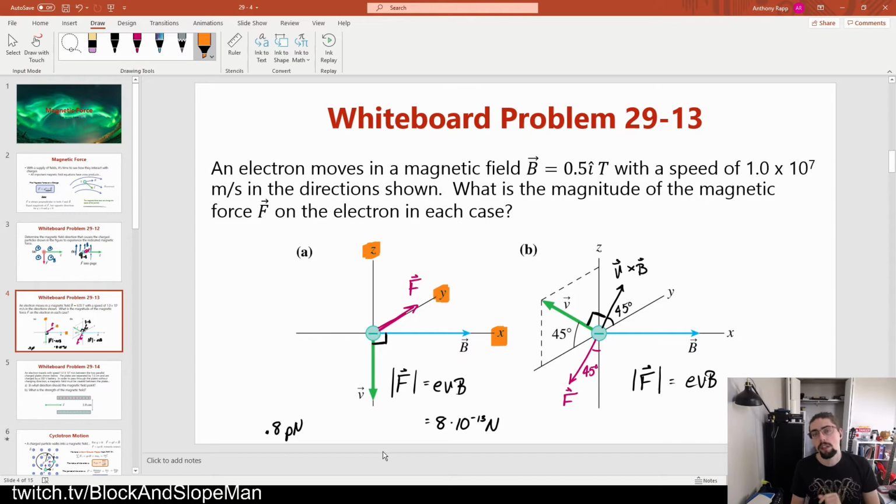The three axes are related by the right-hand rule, and that's why you can't necessarily just draw them out willy-nilly. They're always going to be related in some way like this, right? If I've got X cross Y equal to Z, we can line up our hand and see something like that. We could do some other combination of them, but the three are always related by the right-hand rule. And that's what keeps everything graphically making sense. If we don't have that, then some stuff gets a little bit funky, and there are ways to deal with that, but cross products don't work in the same way anymore, and it's not worth the hassle. Your three axes should always line up in some way with the right-hand rule. And I always just remember X cross Y is equal to Z.